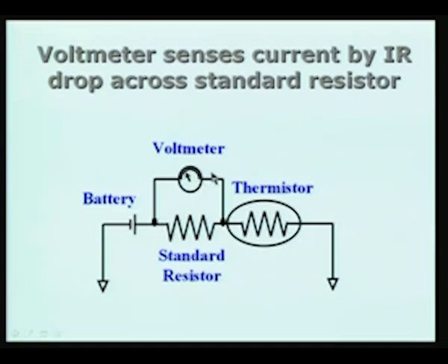Usually, in the case of an automobile, the temperature is not indicated, usually it gives a green and a red. Green is safe and red is not safe, and if it goes to the red region, you stop the car and allow the radiator to cool. So, it is a very useful instrument. Thermistor is used because thermistor is very sensitive to temperature changes.